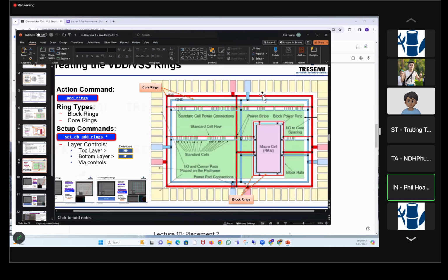But I checked with the DRC LVS guy here. Apparently, it's not on top of their head either. It's just something, if it pops up, you know what rule is violated. But it appears that it is determined by when you build this power ring, you need to have a minimum space between the core and the IO.